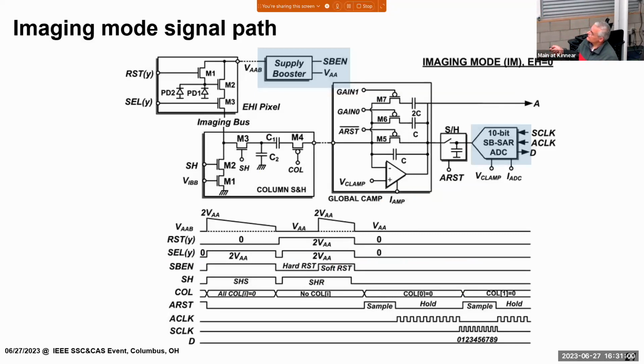for this one, we use a simple PN junction, or N plus and P substrate, to build this pixel. Again, this is a proof of concept first version, and then we spent a lot of time to really improve that energy harvesting using deep N-well and P-well combination and so on, to increase the power harvesting efficiency to make it more self-powered.